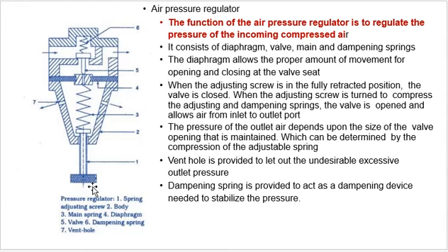So the damping spring is provided to act as a damping device, needed to stabilize the pressure depending on the system. So here is the inlet and here is the outlet. The pressure the system requires can be set by the adjusting screw as per the application, by using the air pressure regulator.